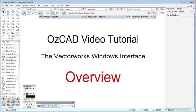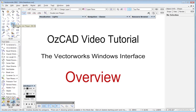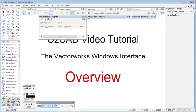The next thing you'll see across the top of the drawing is the mode bar, and the options here will change depending on the tool that you have selected. So with the selection tool active, I'll get the options for that tool. If I choose the double line polygon tool, then I'll get different options. So you need to look across the top of the drawing depending on the tool you have selected to check what options are currently active.